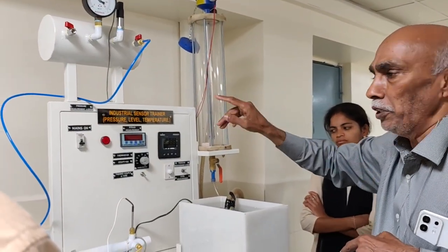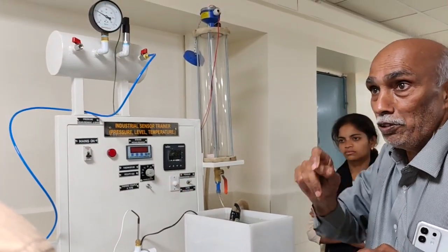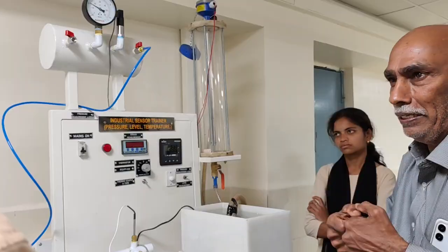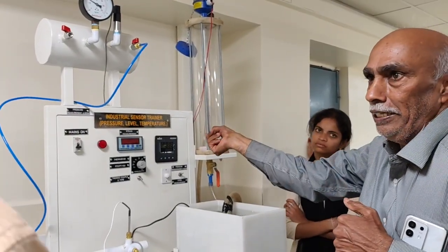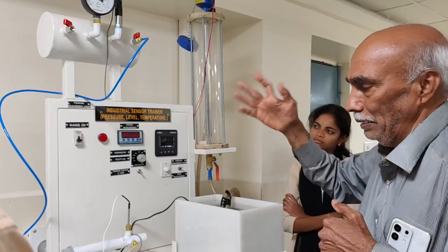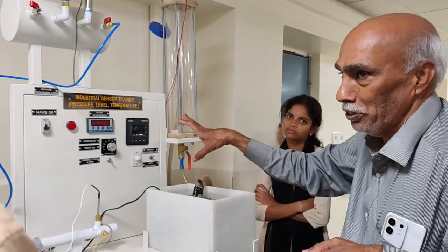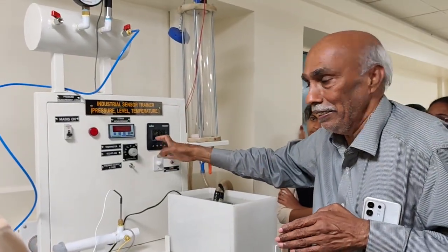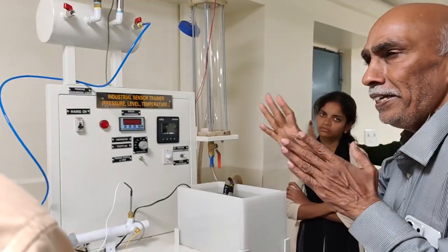Zero is common. Zero display is coming. That means no pressure, zero is coming. That means the current will be around 3.89 to 4, and a 0.01 error will be there in the meter. That is acceptable. That you need to set. Here the basic technique the student has to learn is how to do the scaling: what is the current, how much current, what pressure we are getting, and how to do the setting here. They need to understand that.